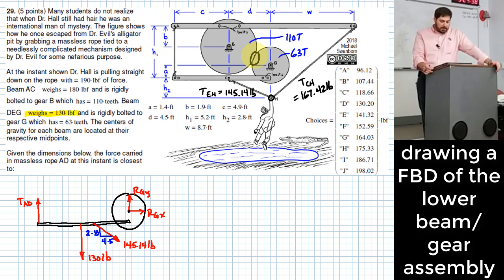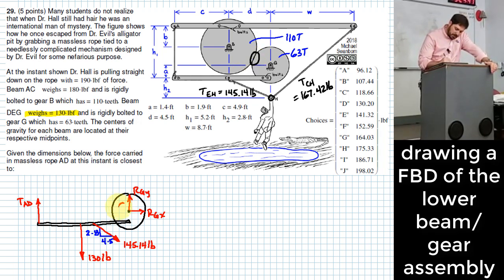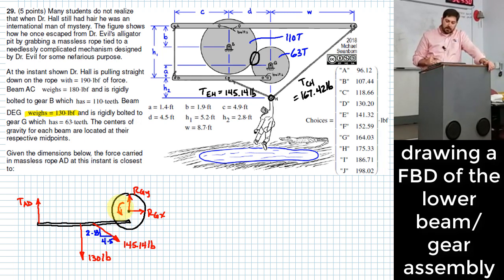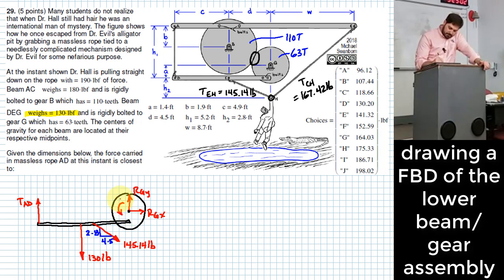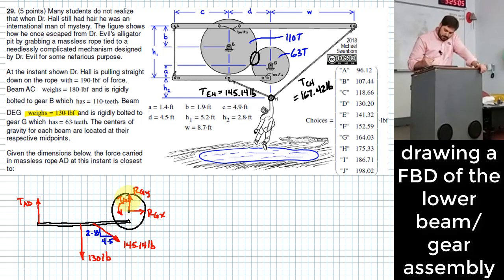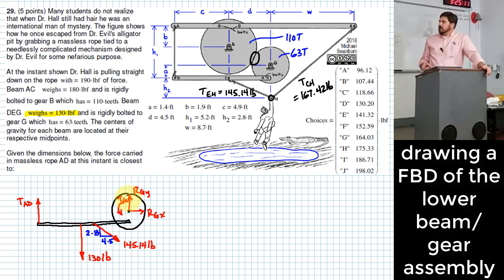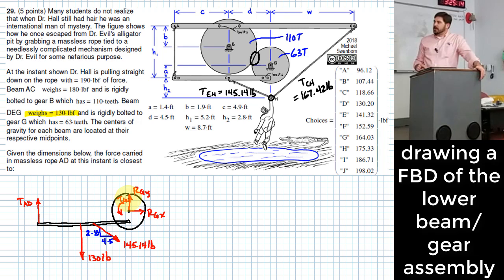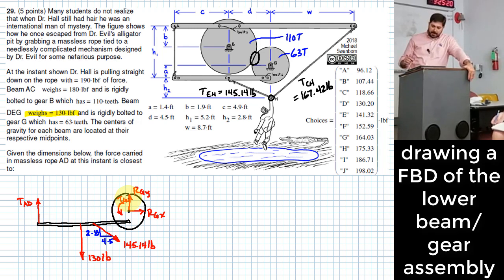All right, so what I'm going to show you is that torque that would happen right there at that interface. We may not know what direction it goes, but I'm just going to assume that it goes a direction. I'm going to pretend like I know that the torque transmitted into gear G is this torque that's applied around the pin, and I'm going to name it TG. Okay. And I think that more or less takes care of all of the different influences that would happen on a body like this. What else should I have on my diagram?